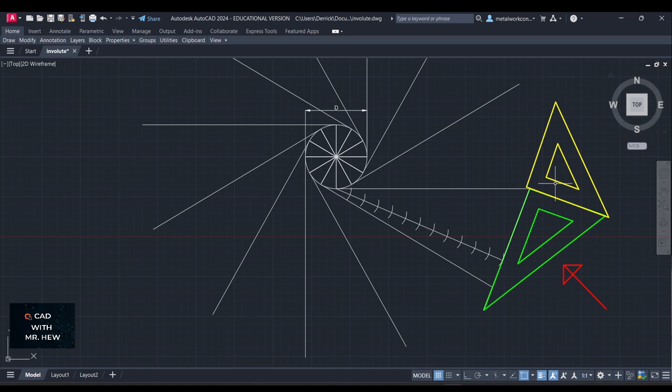You'll be holding the yellow set square and using it as a reference edge, like a permanent T-square until you remove it. And then you use your left hand to slide the green set square in the direction of the red arrow. Okay, is that clear?